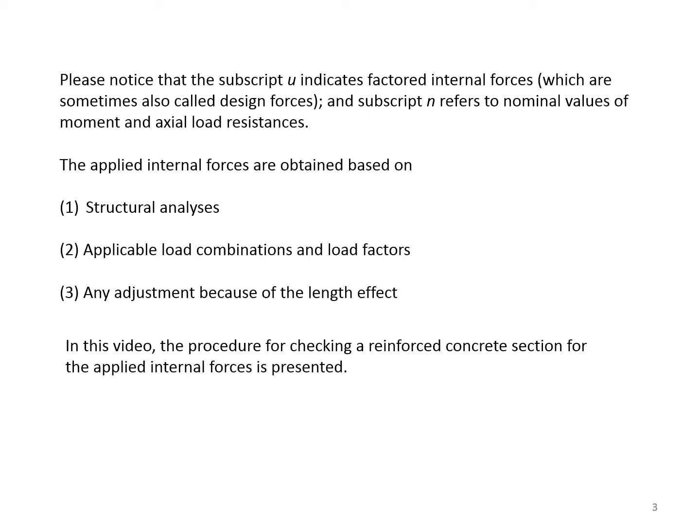Please notice that the subscript u indicates factored internal forces, which are sometimes also called design forces, and subscript n refers to nominal values of moment and axial load resistances. The applied internal forces are obtained based on structural analyses, applicable load combinations and load factors, and any adjustment because of the length effect. In this video, the procedure for checking a reinforced concrete section for the applied internal forces is presented.